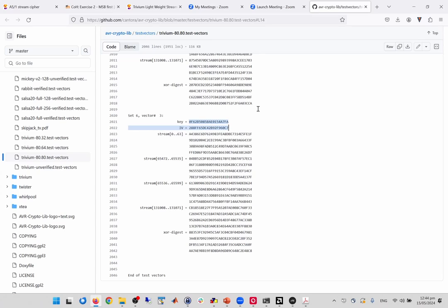If the output is not correctly generated, then you write down the bits of the output that you generate and the output of the test vector, and then find, okay, I actually swapped the bits, or no, I actually swapped the bytes. If the cipher is fully working but doesn't fit the test vectors, then you need to find this way the correct order that you should provide.